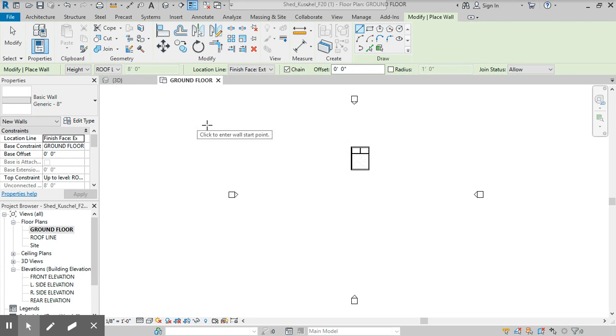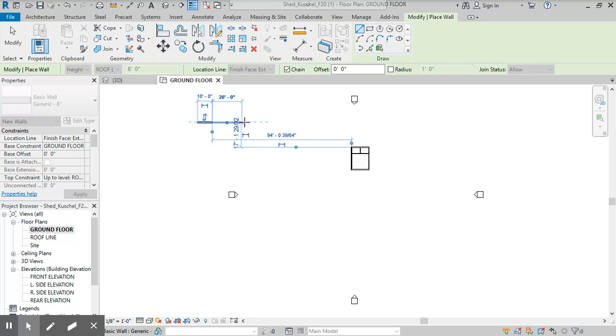Oh, we're going to just draw a wall. Basically what it amounts to is I take my cursor out here and I click and I drag. And notice how the sizes are getting bigger as they go. You can key things in. If I want to make that a 10-foot wall, I just go to my keypad, type in 10, enter. I've got a 10-foot long wall.